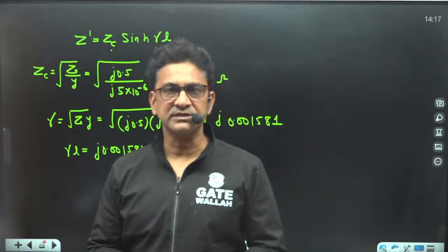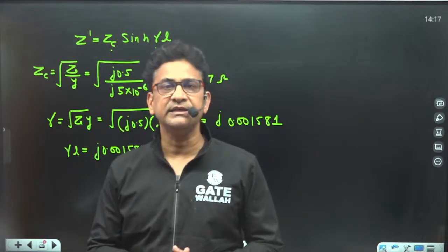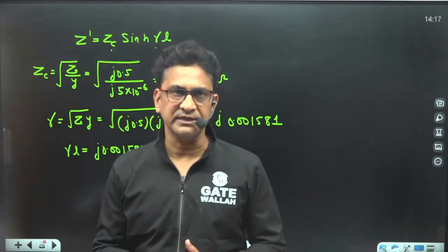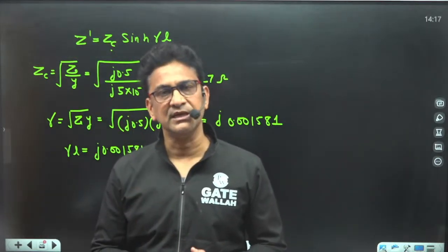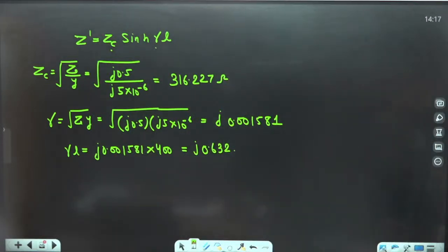So, in the three-phase system, the given quantity is always the line quantity unless it is mentioned that it is a phase quantity. Clear? Even if somebody asks what is the voltage, you will always reply in terms of line voltage only. So, by default, always assume it is a line voltage.